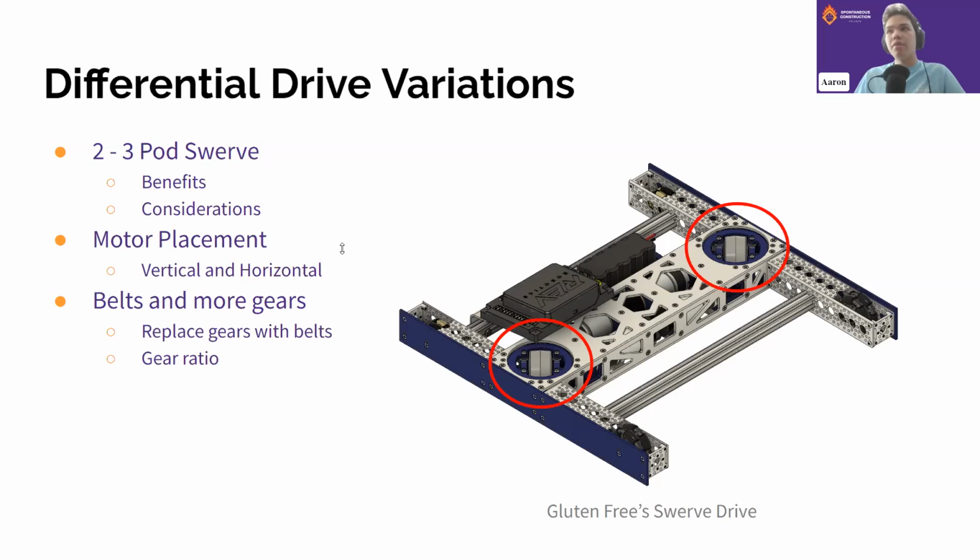Okay, so I would argue that Mecanum Drive is a very general drive that's good for a lot of different games. Basically, any game Mecanum is good at. Well, in terms of Swerve Drive, it's a much more specific drive that is only good for a handful of specific games. So if you're going into a game like Ultimate Goal, if that game was not COVID and Ultimate Goal was in person, Swerve Drive might have actually been a really good option, because being able to push other teams out of the way to get access to the rings and also mess up their shooting would have been a very effective thing to do in terms of playing defense, right?